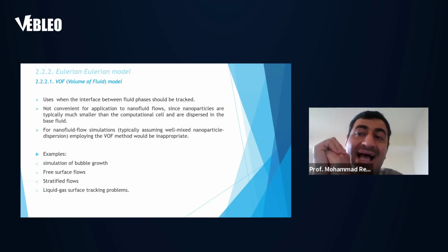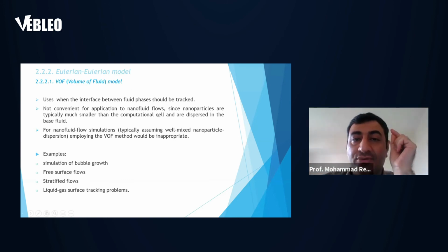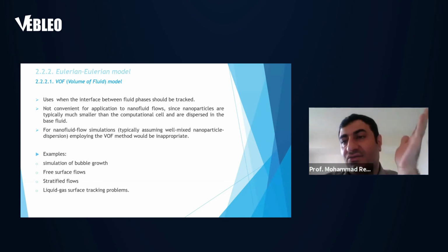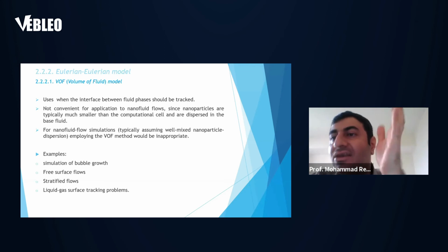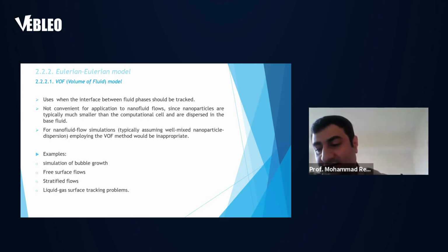The reason is that the size of the nanoparticle is much smaller than the computational cell, and these particles are dispersed in the base fluid. So the VOF model cannot track or consider these particles. Please do not use this model for nanofluid modeling.